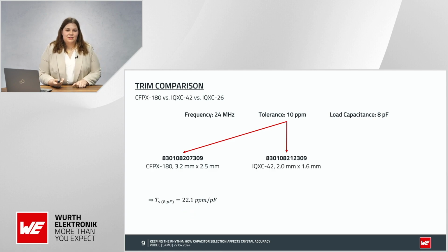Another example, a bit smaller this time, 2 by 1.6 millimeters. Even here, we have a trim sensitivity of 10 ppm. So also this component, if using 1 picofarad of wrong load capacitance, will be out of specification already.